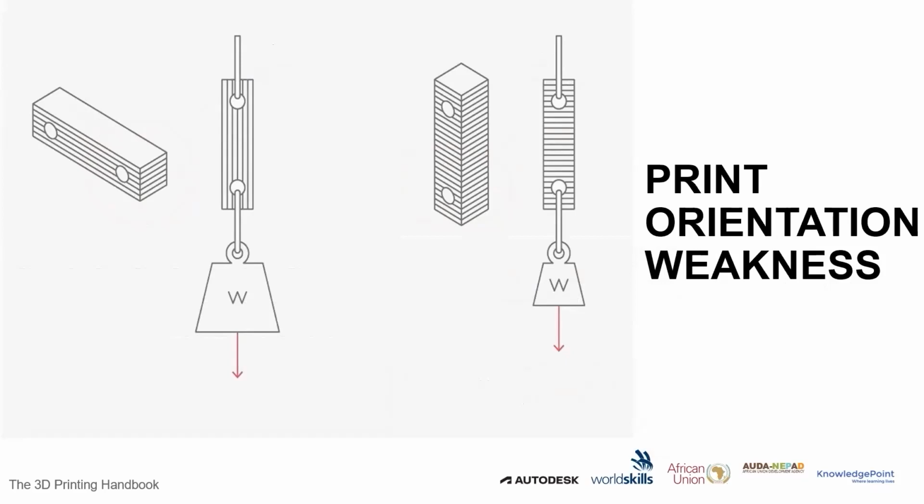So remember, assuming your printing height of a printer is the x-axis, as it's printing, this particular design here is printed layer by layer, and in this direction, moving this direction. Now, what it means is, if you are going to have a force, really pay attention. If my design is going to undergo, let's say, tensional stress, with a load attached here and a load attached here on both sides, the weakest point of any 3D printed object is the point of adhesion, which is this layer by layer.